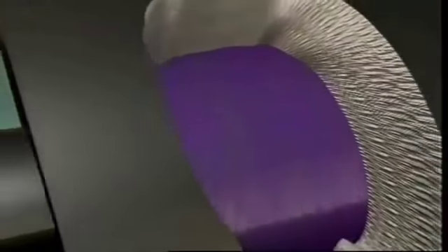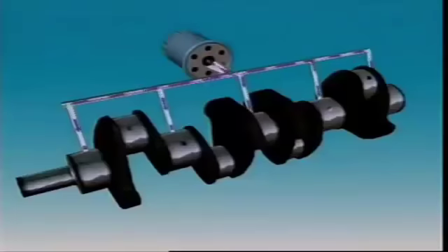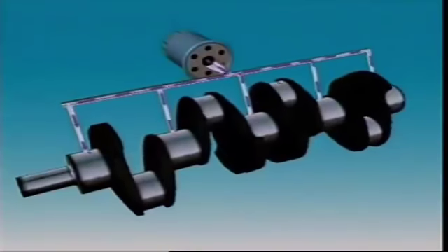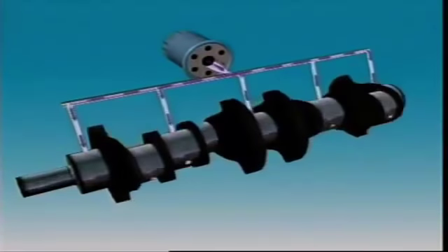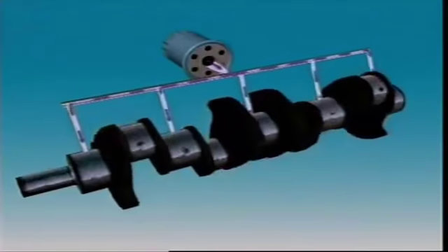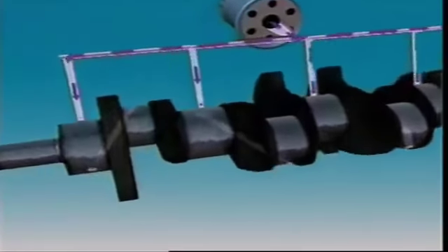Under normal running conditions, spinning shafts ride on a microscopic wedge of oil. Oil flows through a long gallery in the cylinder block. Each main bearing has its own oil supply passageway from this gallery. Passageways drilled in the crankshaft carry oil from the main bearing journals to rod journals. Oil flow maintains the oil wedge between the shaft and bearing and carries away particles that could cause wear.